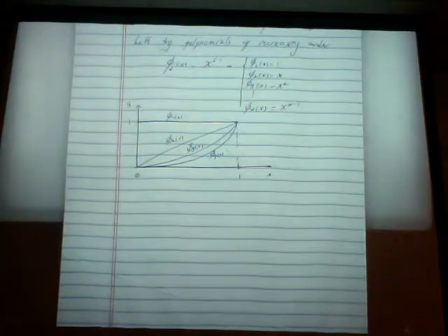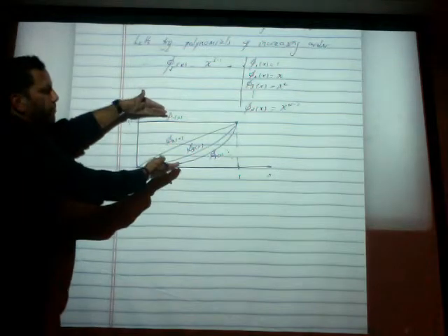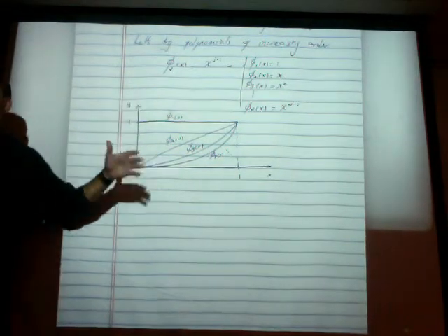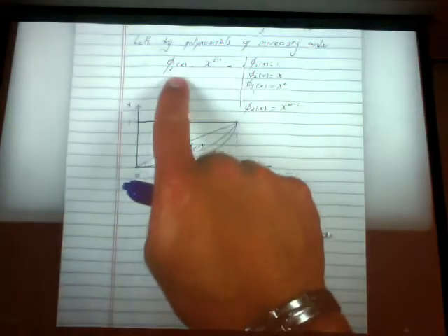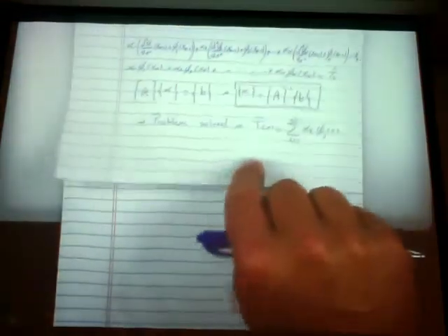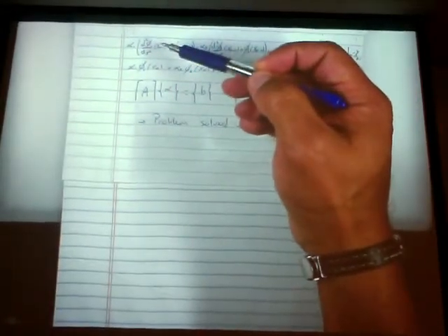So somehow, we're going to build a temperature that we don't know what it looks like, supposedly, and we just have constraints, which is the governing equation and boundary conditions, that is a combination of these functions here, and somehow we're going to make up what it really looks like. So we need not only the trial functions, but in the algorithm, notice, we need the second derivative of the trial function. Okay?